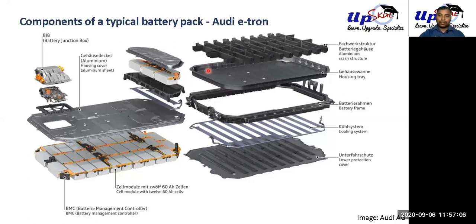Maybe for the lower side there is no insulation, because we need to transfer heat on the lower side. Instead of insulation, there will be a thermal paste. Same paste, if you have ever repaired your computer for overheating, the mechanic actually applies a metallic paste. This thermal paste improves conductivity between two surfaces, so that is applied below the batteries. On the top side, most likely there will be an insulating material that is also fireproof.